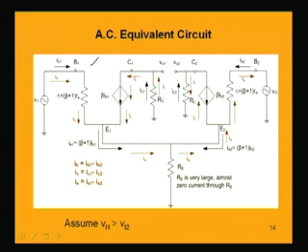And if we look into the directions of current in the transistor Q1, Ib1 and Ic1, that is the current which flows through the collector resistance, and it will be joined by the base current Ib1 at the emitter point, and the current flowing will be Ie1, beta plus 1 into Ib1, which is equal to nothing but Ib1 plus Ic1. So, this corresponds to transistor Q1's currents.